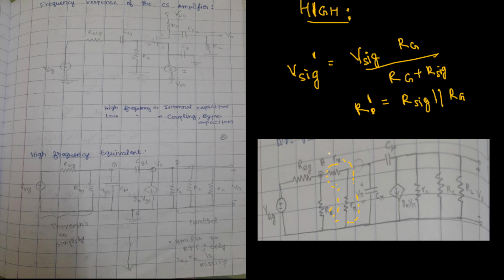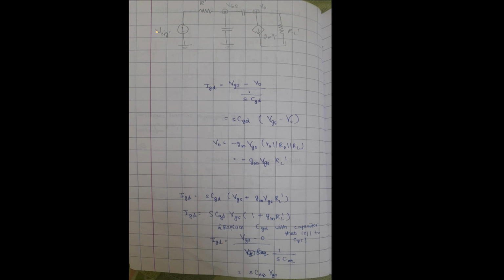So we reduce this entire circuit into just one voltage source and one resistor in series with the voltage source. Right, so we have simplified this circuit now. This ground doesn't really mean anything, so you can just join this whole thing to avoid confusion.